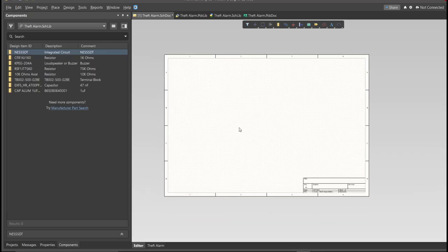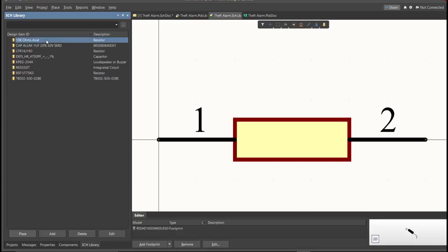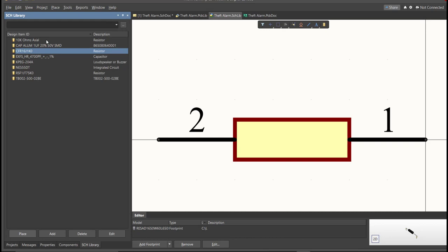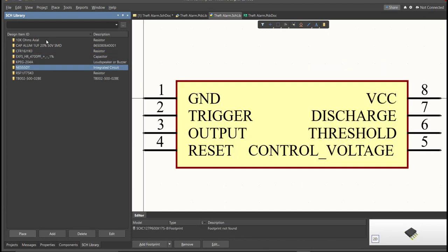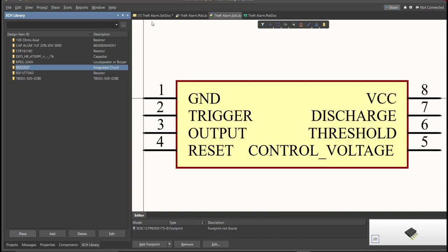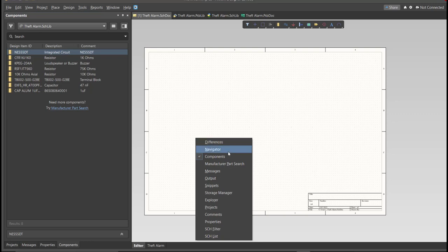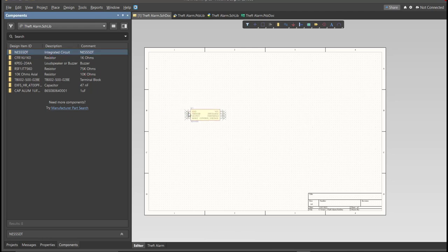After you finish all the components in the BOM list using a library loader, you can check here in schematic library panel all the added libraries. So these are the added libraries for this PCB. Next, we're going to put all of this in our schematic doc. So go back to the schematic doc and click on components. If there is no component in your panel, just press K in your keyboard, then click on components. Now you can see here the library for this project. So we're just gonna drag the library inside the schematic sheet.